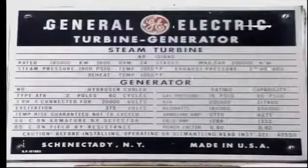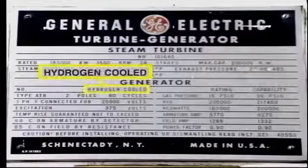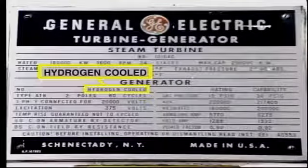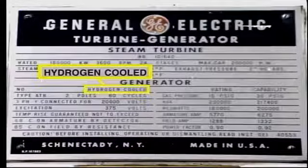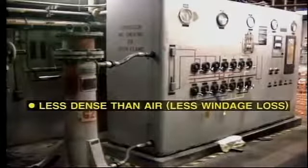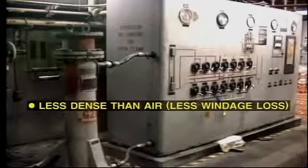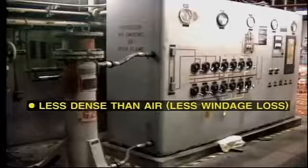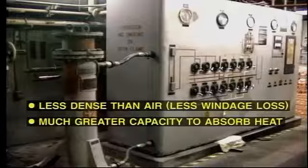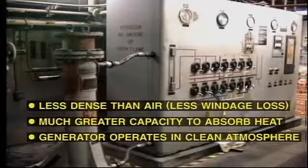Well, so much for air cooling. Let's now turn our attention to hydrogen-cooled generators. When the unit size increases above, say, 100 megawatts, hydrogen cooling is normally employed. There are several advantages to using hydrogen as a cooling medium instead of air. Hydrogen is less dense than air, and consequently the windage loss, that is, friction loss due to rotation of the rotor, is considerably reduced. Hydrogen has a much greater capacity to absorb heat than air. Therefore, it is a better cooling medium. The generator operates in a very clean atmosphere.